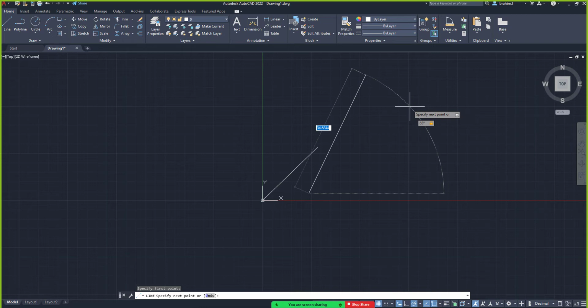So like I said, we have different methods of entering commands on AutoCAD, the way we input data on AutoCAD. The first one we just practiced, which is entering the data by entering the XY coordinates in the axis for the length. It's called the absolute coordinate. Are you with me? So we have the absolute coordinate, we have the relative coordinate.